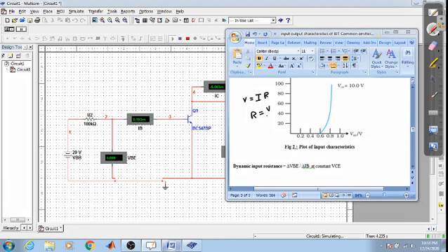So we are calculating this resistance. Calculating this resistance at what? Input. We are calculating the resistance at the input. So it's called what? Dynamic input resistance. You are calculating the resistance at input, and the calculation is dynamic. It is changing. So the change, delta VB, to the change, delta IB. IB is also changing as VB is changing.